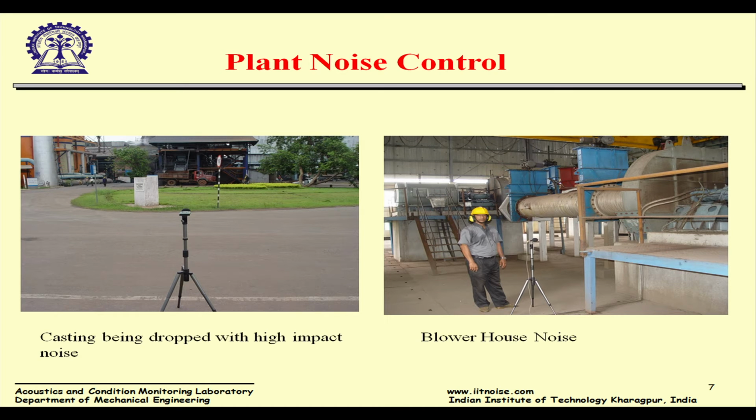That is one issue where the environmental industrial noise in that plant goes up because of this dropping impact. So there was a design where we had a hydraulic mechanism for the bed of the truck to go up so that the drop height reduces, and then the impact noise would reduce, the potential energy would come down, and that noise would just reduce.